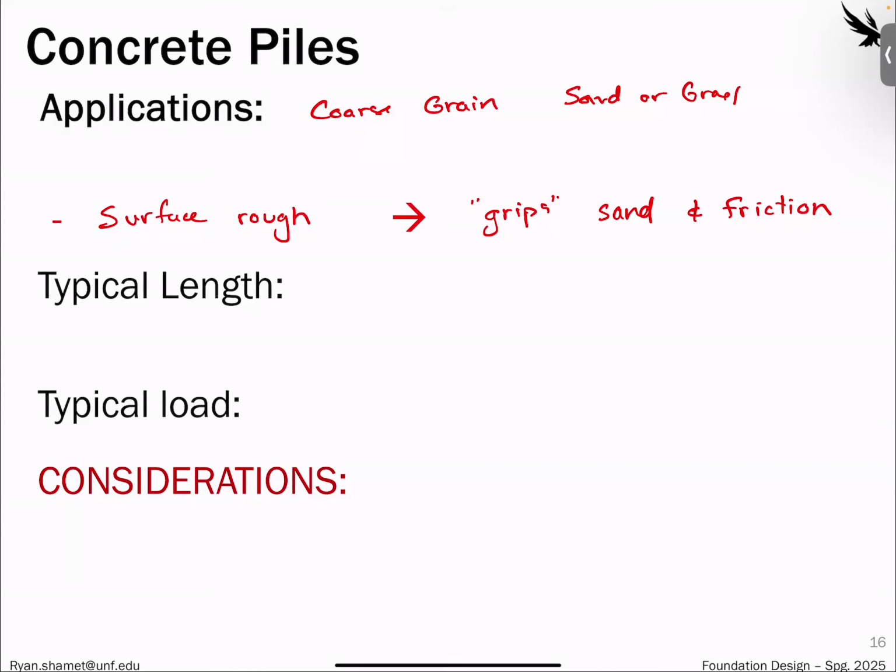So the typical length of this is basically the same as before. Mainly going to be 30 to 40 foot individually max. But I mean, you've driven on the highway at like 2 a.m. You've probably seen those massive trucks taking them. You can get the 80 to 100 foot length piles. You just have to get specialized transportation on it for precast.